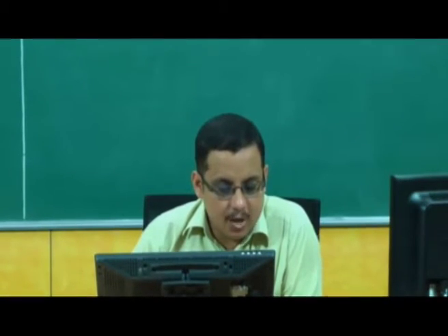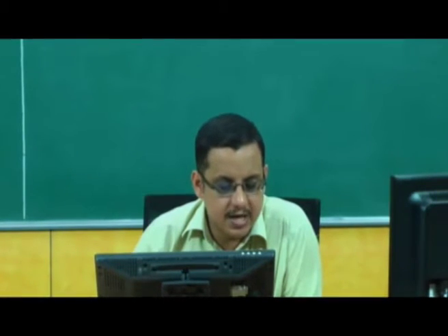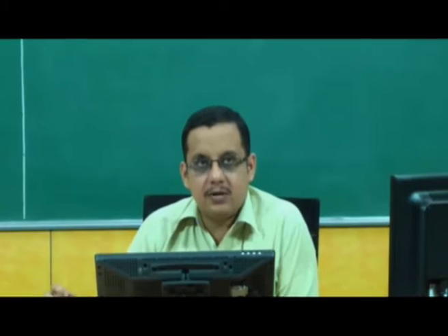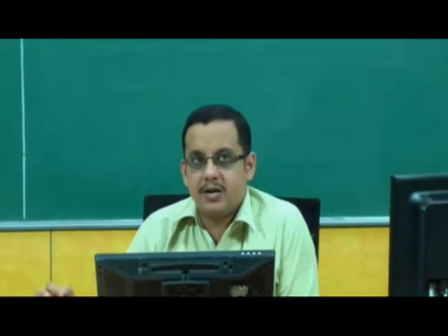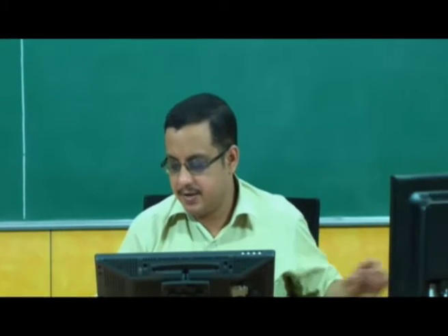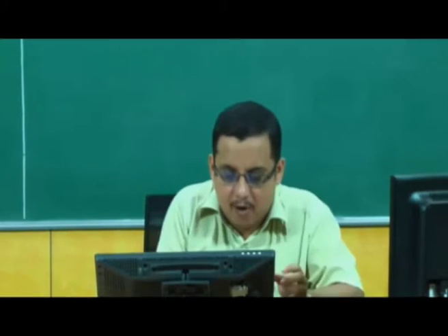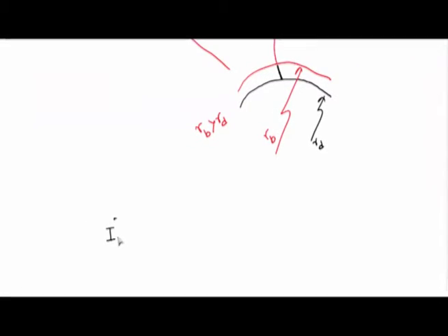So the next question is, if the pitch point is not constant but the ratio of instantaneous centers remains constant, then is it possible to construct a gear profile? That is actually not possible. The ratio cannot remain constant if the pitch point does not remain constant, because if you recollect, the geometry is: I12 is fixed, I13 is also fixed.